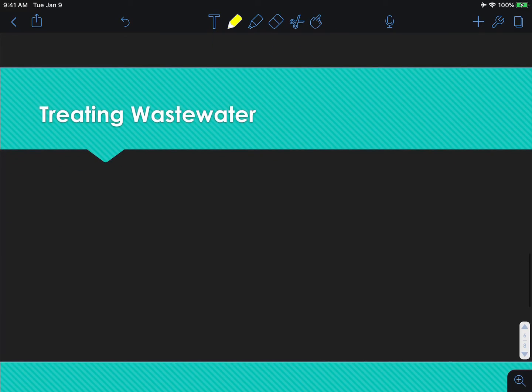Next, I want to talk about treatment of water, and one thing we saw in our book was treatment of wastewater. The book talks about primary versus secondary treatment of wastewater. Primary you can think about as basically physical operations to remove the floating material and stuff that settles, that's bulk waste, if you will, bulk stuff that has to be removed.